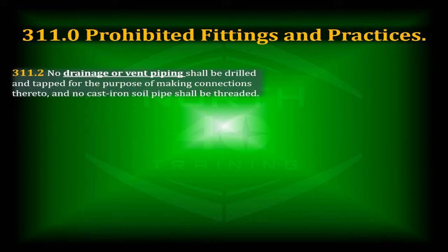311, prohibited fittings and practices. 311.2, no drainage or vent piping shall be drilled and tapped for the purpose of making connections thereto, and no cast iron soil pipe shall be threaded.